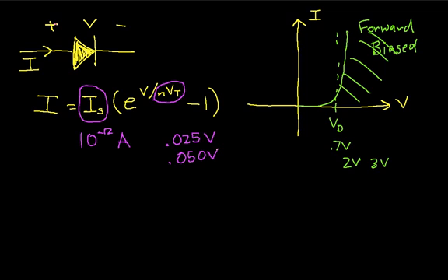Okay, now if the voltage is negative, you can see from this expression that the diode current is also negative, but it's very, very small. So for negative voltages, you get a small current. This current's often called a leakage current, until you get out to some point out here, called V sub BT. So this is actually what they call a breakdown threshold. And at this point, the VI curve goes like this.